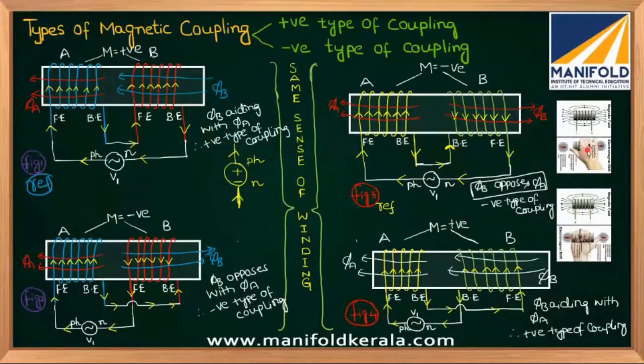Whenever it's entering at the front end, you have to hold core in this manner. Okay, guys. If a core is horizontal, here we are holding like this. If it is vertical, you can hold once again in the same manner. But thumb will come what? Okay, I'll ask one question. If current is entering at front end, if core is horizontal, you're getting direction of flux right to left, no? Very good. Suppose the core is a vertical shape, once again current is entering at front end. At that time, what is the direction of thumb? Will it be upwards or downwards?